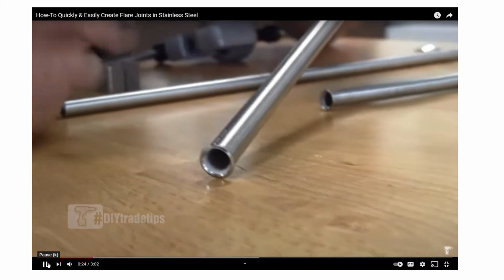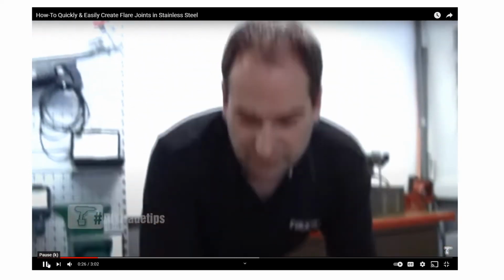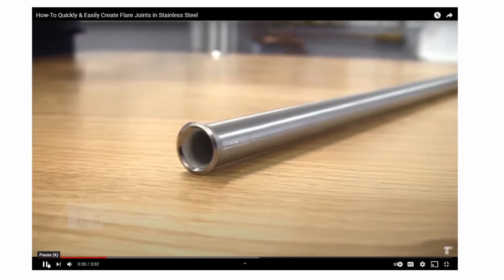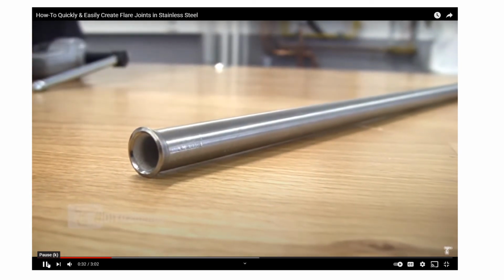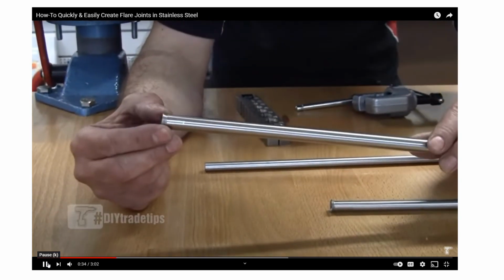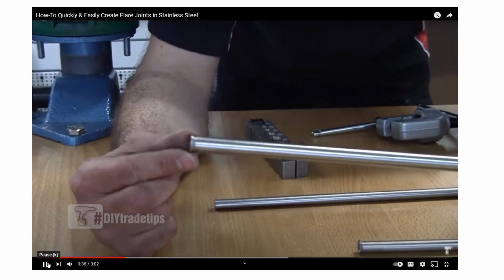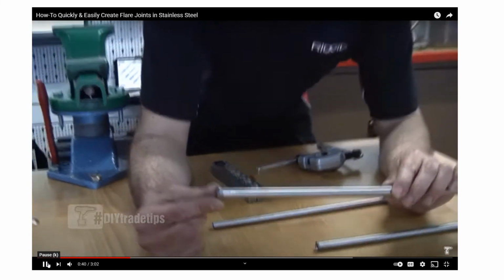Instead of using a simple compression fitting with an olive, a flare actually uses a cone seat, and that's the idea of the flare. The flare sits onto a cone seat fitting. So they're very popular with hydraulics type applications. Even things like brake lines in vehicles often use flared ends.